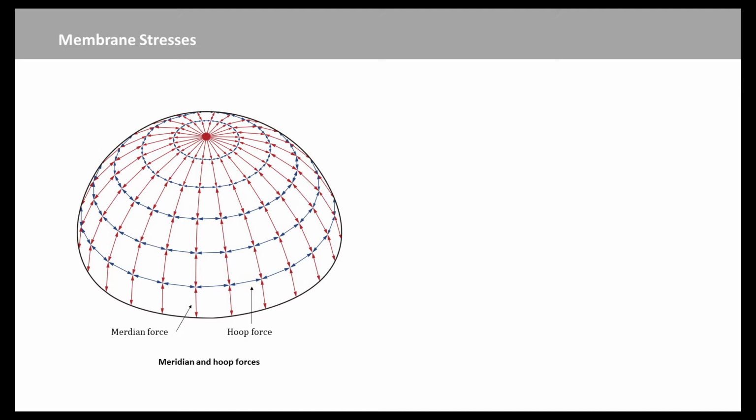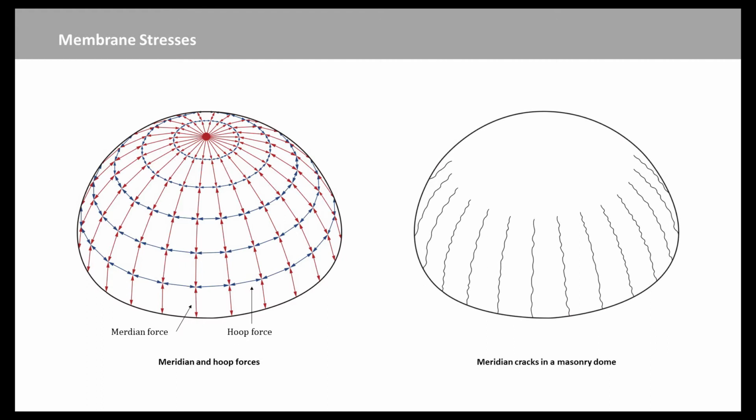Initial membrane stresses occur in the dome's rotational shells. Later, the masonry dome probably cracks when the tension stresses in the hoop rings near the spring, usually fading in the course of time. The initial membrane equilibrium is thereby lost, and meridian cracks will arise and spread along the dome. The emergence of thrust is the main consequence of cracking of the hemispherical domes.